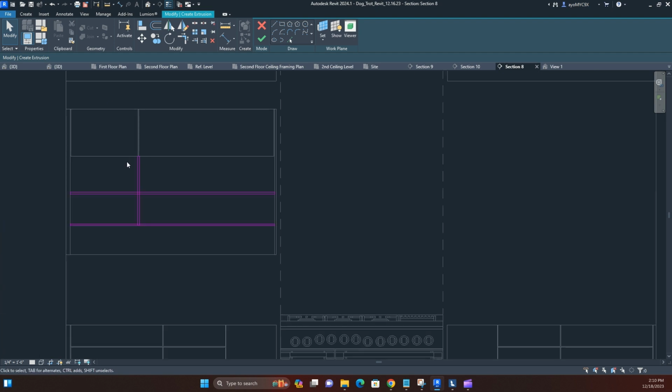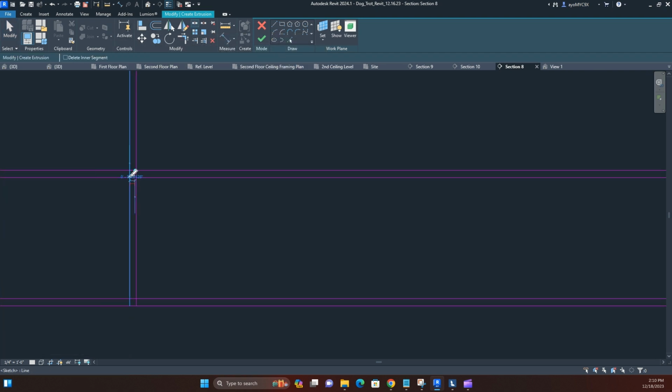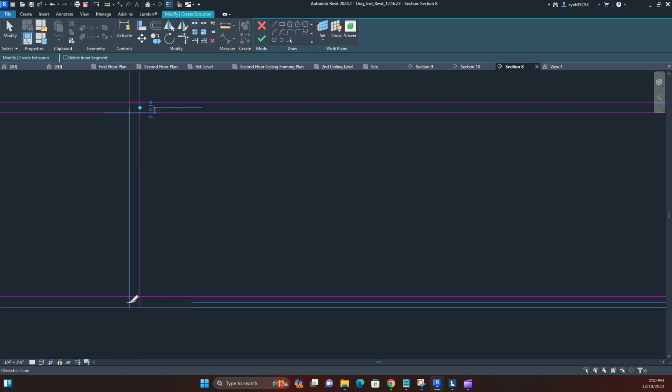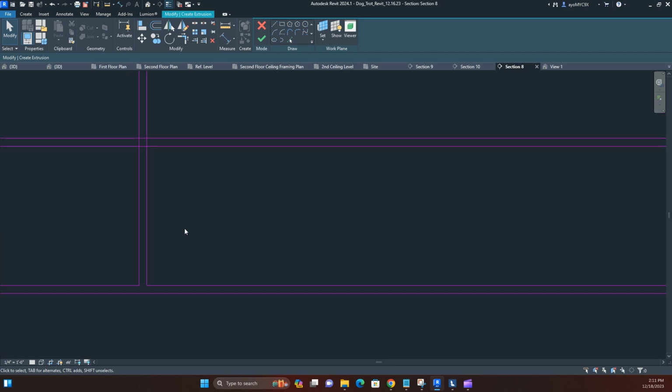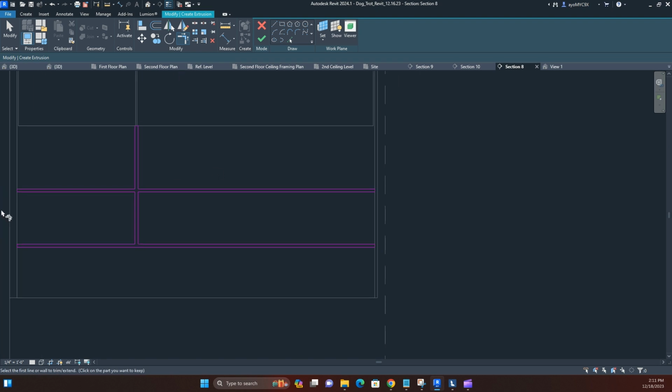So 0.5 inch over there, I need to cut it because it has to be one big void, right? So I use my split command, trim and extend it. Do the same at the top. I need to trim and extend at the top as well. TR is a shortcut for that. Looking good. I think, yeah, it's one big void now. So I could apply the material again.